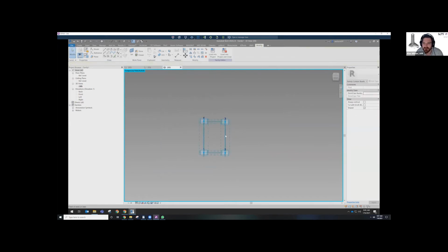The modeling environment in adaptive panels is reasonably similar to the massing environment if you're familiar with that. You can see here by selecting the points, I have my create form option. There are different ways to create form, which will automatically generate based off what you have selected. So for example, if you have 4 points like here and I click create form, I can give it a thickness or just make it a single panel. It'll give it a set distance for the offset. Here it's 2000 mils, or 2 meters. You can change it here to 1000, things like that.